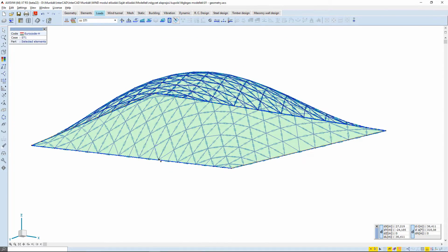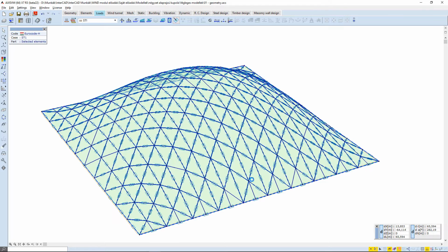The module is primarily designed to determine external pressure factors, so it is advisable to cover openings with load panels in the case of complex interior structures. However, simple interior buildings such as a hangar or unenclosed truss structures can be analyzed without issues.